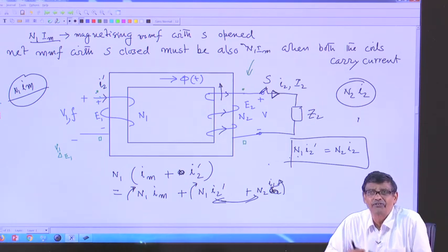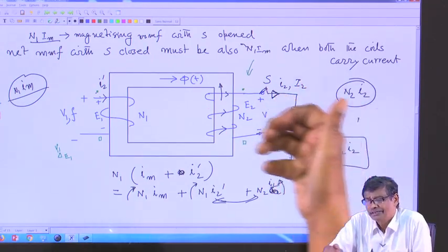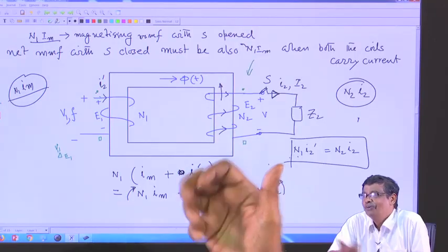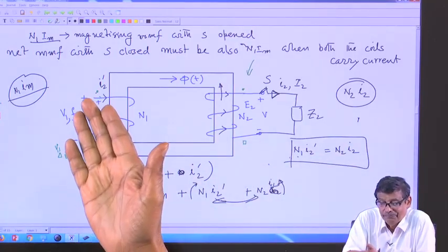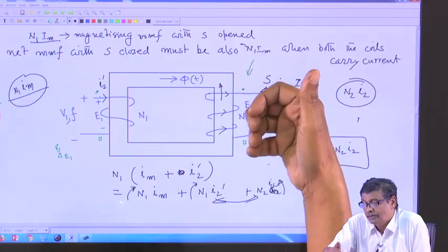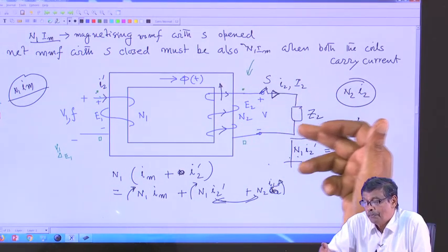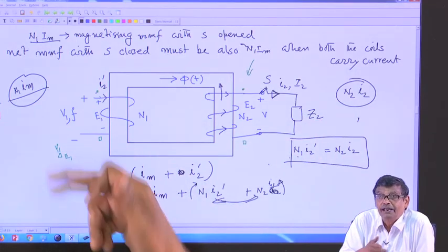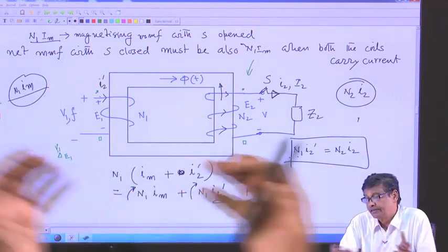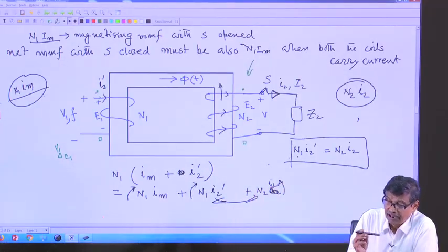There is an easier way of understanding that. Look here, if you draw power output from the secondary of the transformer, primary current must increase. How can it? Because these are the only 2 points where I am pumping power into the system, and you are taking power out of the system between these two. Therefore, if you consume power here, ultimately power has to come from this place here. Therefore, this power must balance. We will discuss those things later, but I hope you have understood.